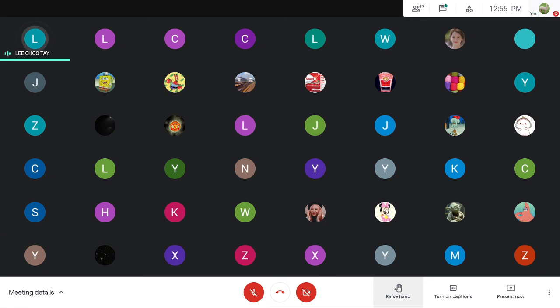And for FSK, we transmit 1 with one frequency, and we transmit 0 with another frequency, correct? So the average SNR means that we transmit ASK and FSK with the same average signal power.